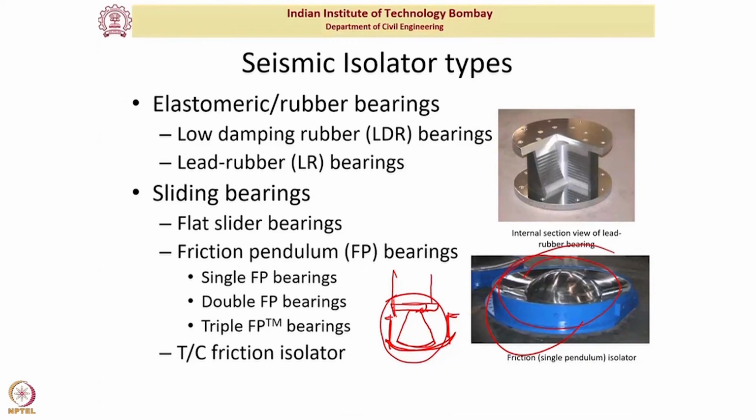For seismic isolation, it needs to accommodate large deformation capacity. Because even for seismic isolation application, if you look at it, these steel surfaces, that accumulation of dust is a big issue. So here what they do, they use a cover. So the overall thing is actually covered inside a closed enclosure. And this surface here is polished, and there is a layer, basically a polymer layer, that is applied on this surface.